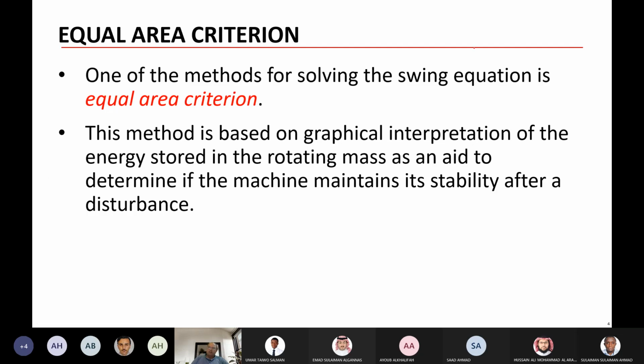You have here the generator. You have mechanical power input and electrical power output, and you have the swing equation, the acceleration power equal to Pm minus Pe. So you are analyzing this. If Pm is higher than Pe, the kinetic energy will increase, and this is equal to J d square delta by dt square. Trying to convert this to M and to H and so on, but anyway, you have here H over pi f0, no problem. So this is the acceleration.